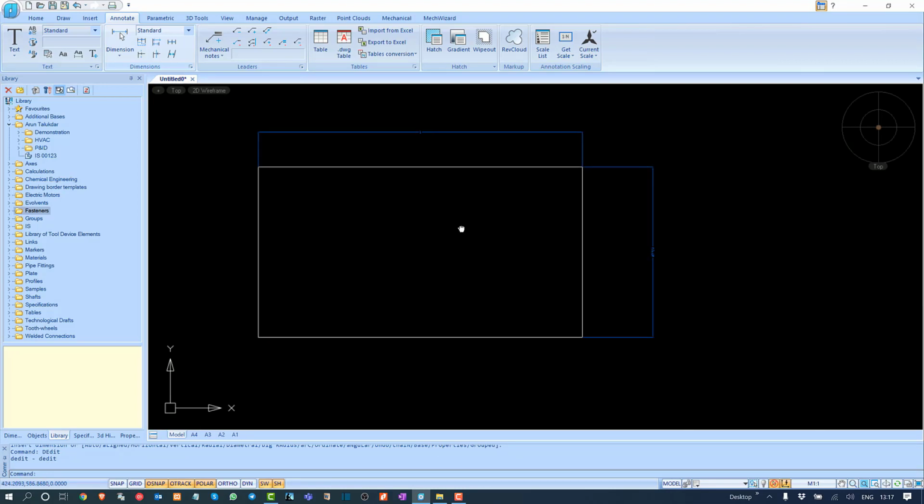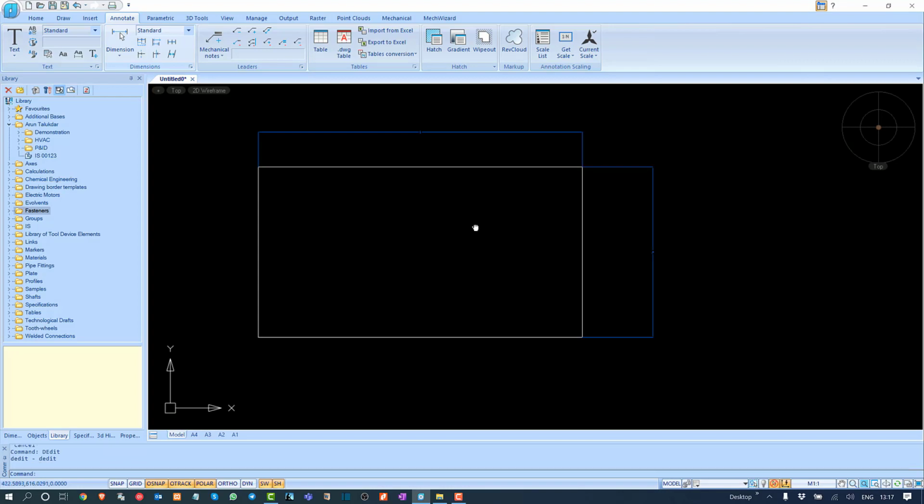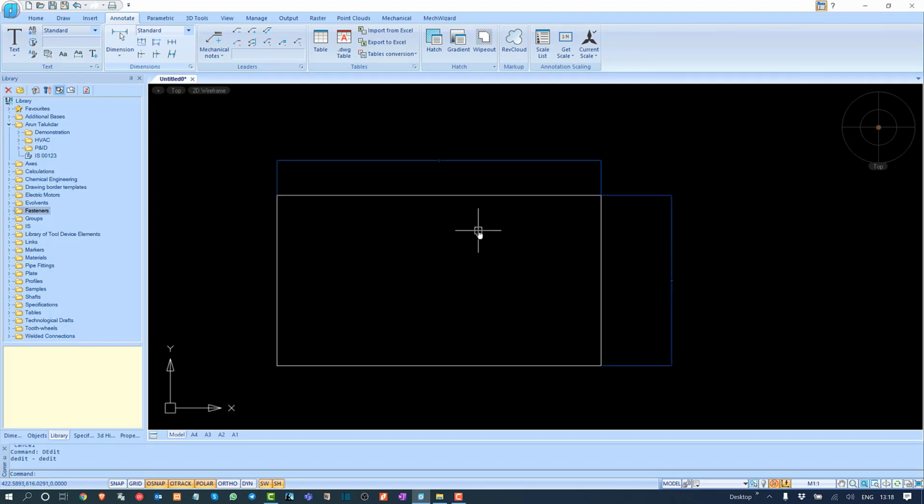In complex objects or in simple objects, we will have to convert all the variable dimensions, the ones by which the object can deform. We'll have to replace those dimensions in terms of variables, and we will have to define relations between those variables, right? So likewise, I will say this is not 200, close to 200, so we'll make it W. So now I'll say okay. So now I have two variables, and I know this object needs only two variables to reform.